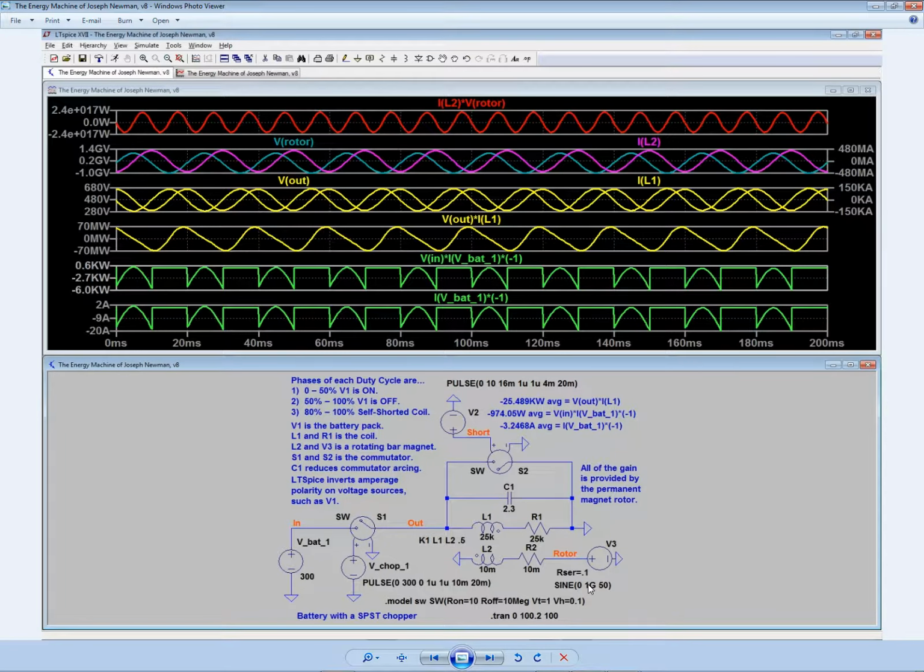So I wouldn't expect that the rotating bar magnet actually has a gigavolt, but who knows, it's probably something similar. So that's why I don't worry about the details of how I produce these waves. The important thing to me was no longer how I create them, but just that I create them. And the inductance on the coil and its resistance is very close to what Dr. Hastings in Chapter 6 was measuring: 16 kilohenries and 50 kiloohms on that coil. And it was just a measly little 145-pound coil with a 14-pound bar magnet.